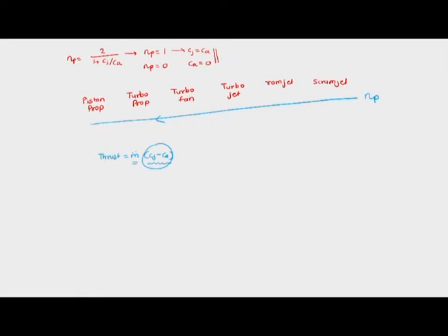But their belief, their design, is upon increasing the kinetic energy more, or increasing the velocity more. But then there can be one more way to increase the thrust without changing much: (Cj minus Ca), but deal with a large amount of mass of air. In this category we have turboprop and piston prop. These are propeller based aircrafts. We are going to see these aircrafts in the next class, but this class is mainly upon the cycle.